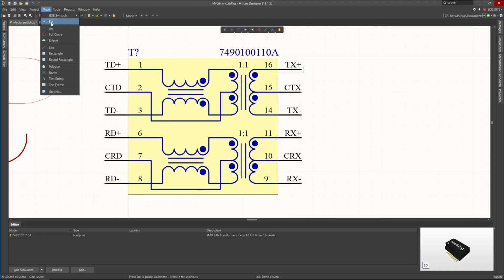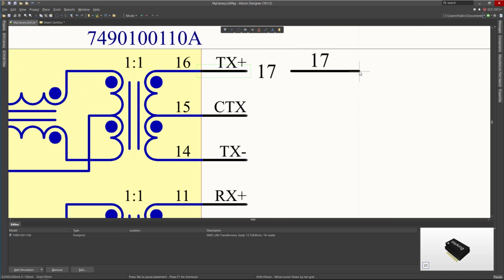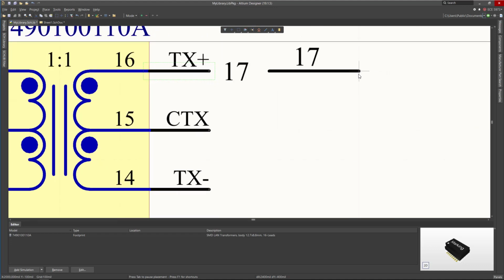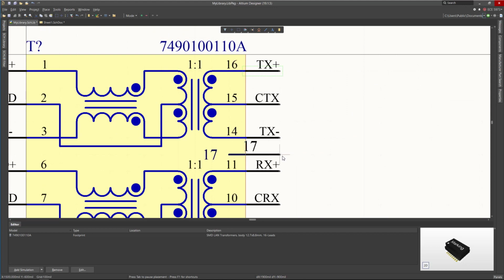So when you click on pin placement, this has to be snapped into a 50 mil or 100 mil grid, and 100 mil is always preferred, as you can see in here. And the handle where this pin is held is basically the electrical connection. As you can see, you have this cross in here. This is the electrical connection, and this has to be on the outside like that. And here you can connect with the rest of the circuit.